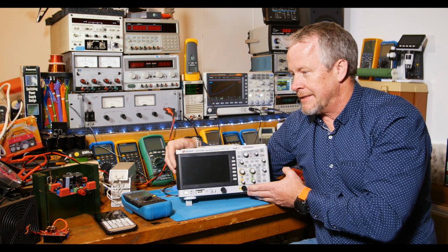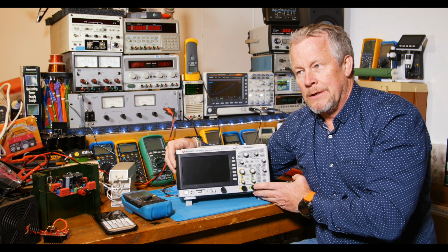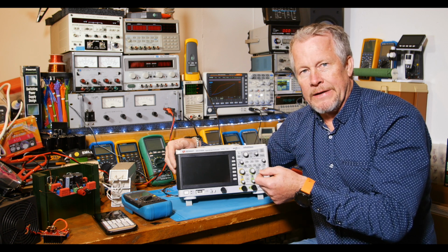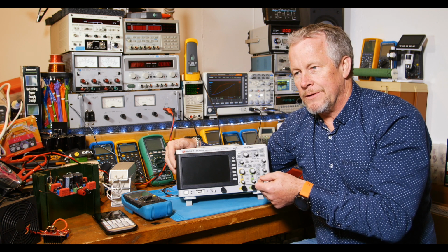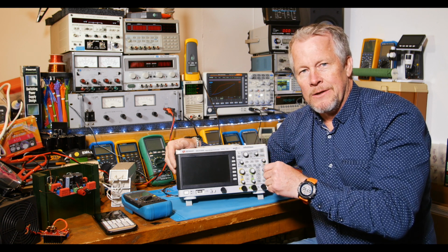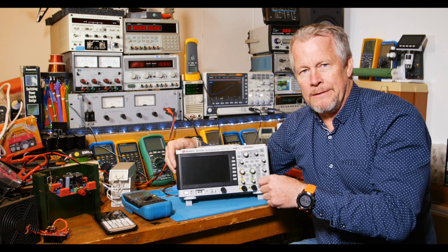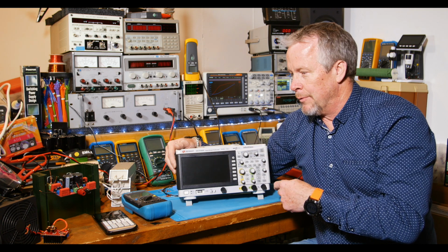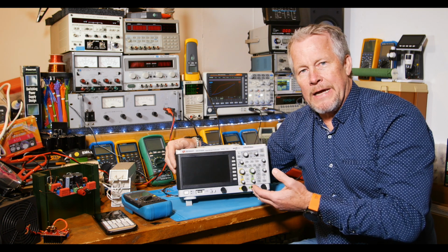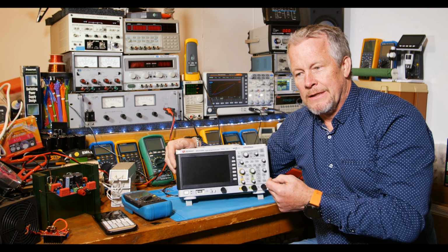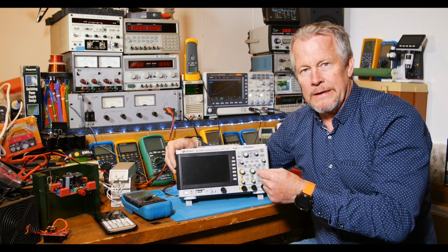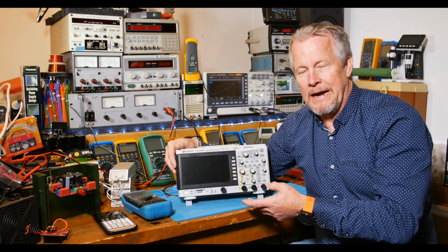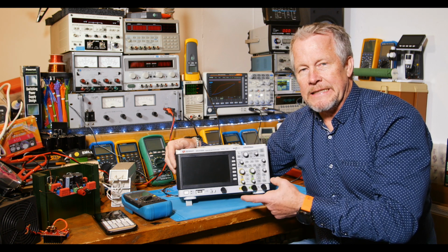It can do a lot of things, even things as simple and useful as looking at, say, a curve of an inductor. Okay, well, you say you could just plot that. You just do 2 times pi times frequency times inductance, that's X of L. I can just plot that. Well, the thing is, though, you have parasitics, right? There's some resistance in that inductor, so you say, okay, I can do a little more math and take account for that DC resistance, DCR.